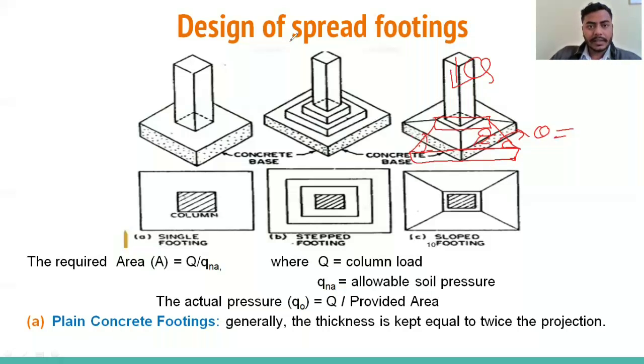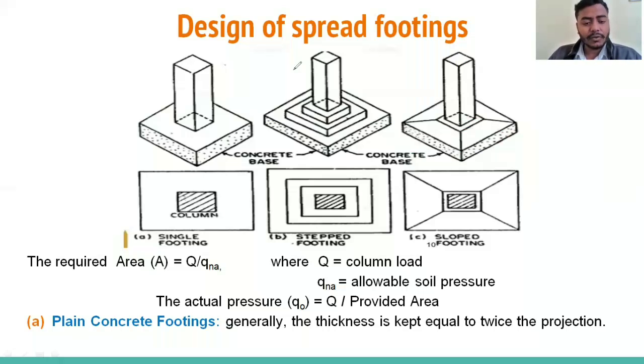Okay, so now we will discuss how to design. This isolated footing will also be designed in two-way. We can design it as a plain concrete footing, and we can also design reinforced concrete footing. Whenever the load is low and we have enough bearing capacity of soil that will resist the load coming, then we can design the isolated footing as a plain concrete footing.